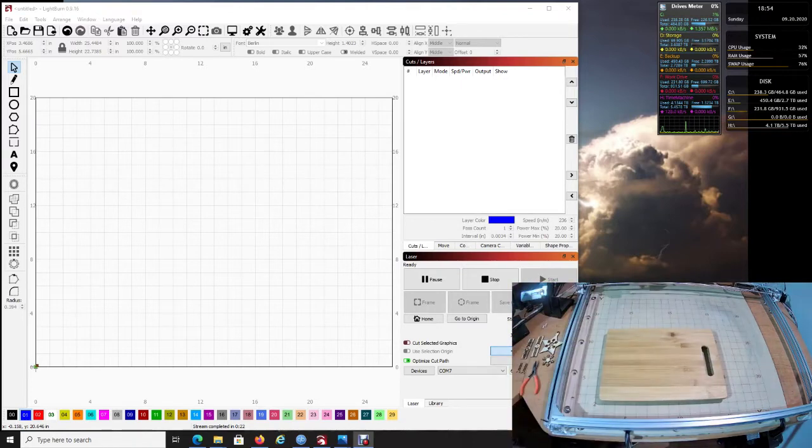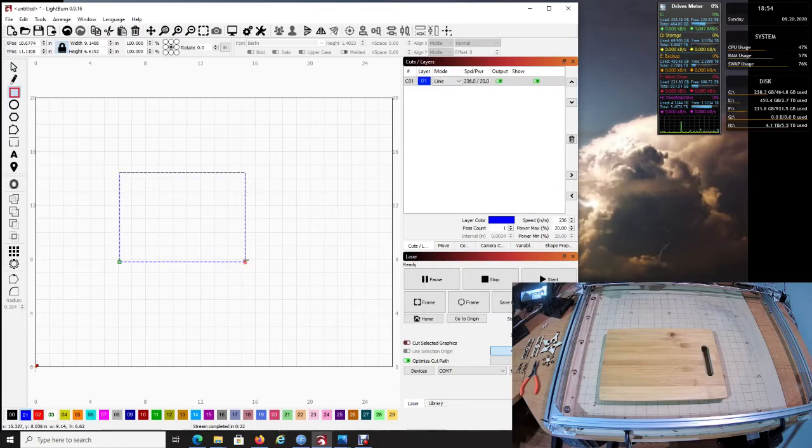So what I do is come over to my software, and I create a rectangle just anywhere. Click on rectangle here, just drag and drop your mouse. It doesn't matter where you do it. And let's unlock it. So up here we're going to unlock it, and the width, we're going to change to 9. And the height we're going to make, let's just do 8.1. So now that we have the exact width and height, let's lock it again.